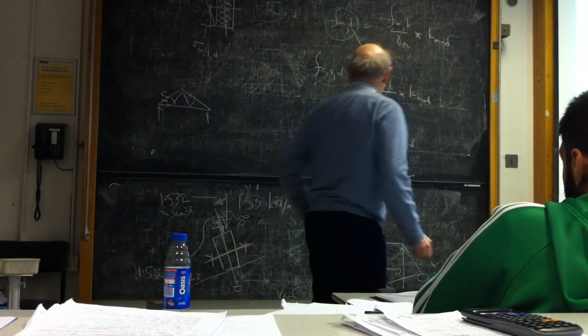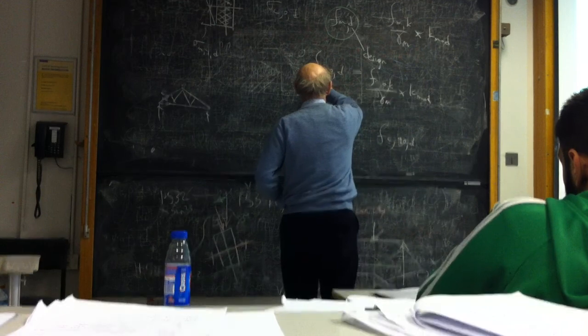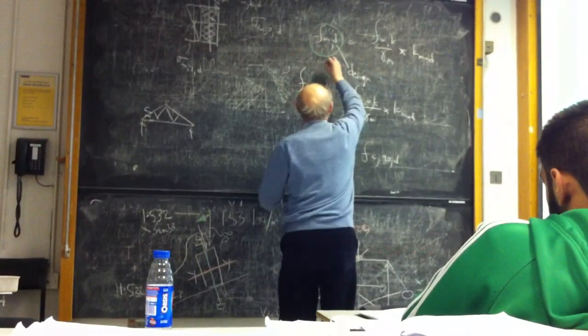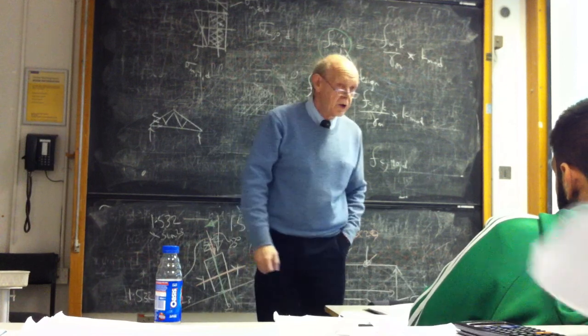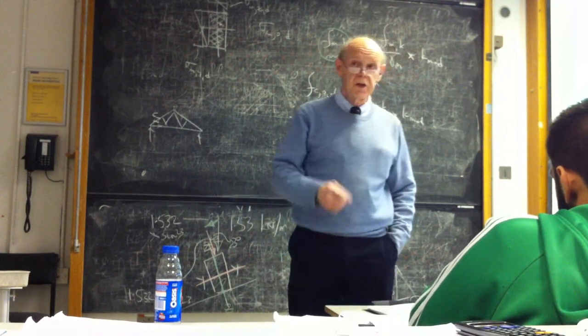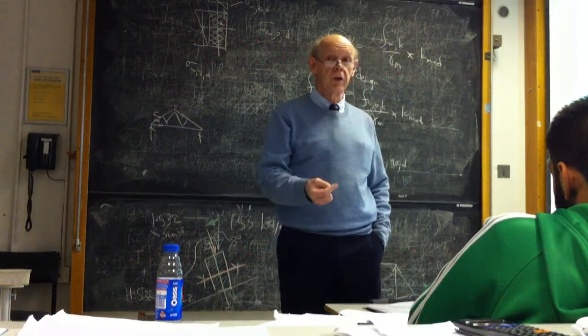These two. Right, now if you're dealing with a column, we've got these values, that one and that one. But when we come to apply them to the column, the first thing we've got to do is modify them because the column might buckle.